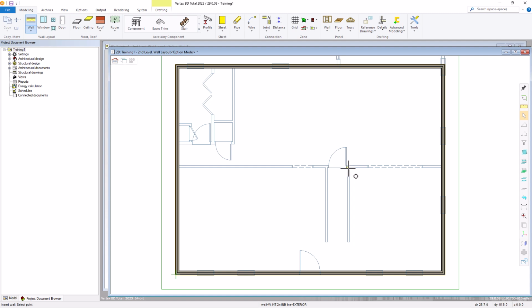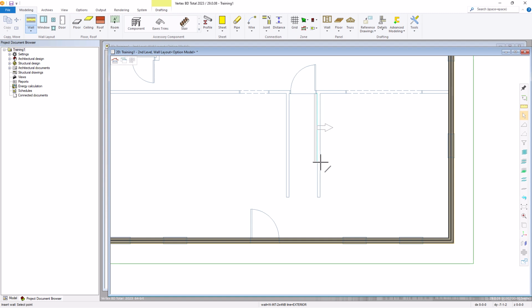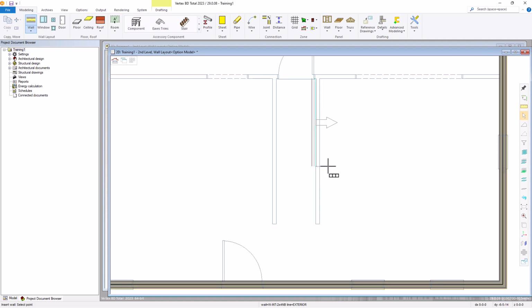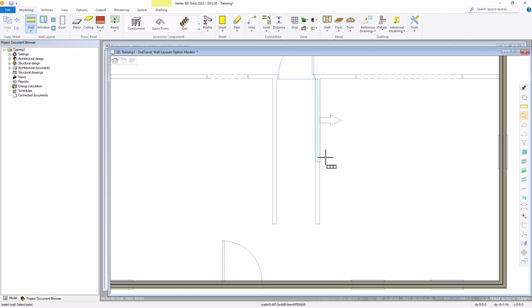Let's select this first wall. Get that yellow icon, we can zoom in. Lock it in the Y-axis by hitting the I key. Our wall isn't lined up correctly, so we'll need to right-click and select the opposite placement to align the wall with the reference drawing. And we'll just bring that wall all the way down to the exterior wall. V to confirm, and add the other wall.